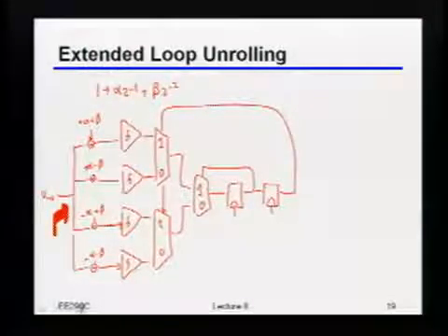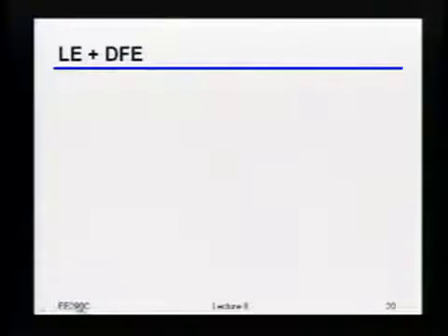Okay, so there were just a few practical issues that I wanted to briefly mention. This one I think we mentioned a little bit last time already, but just to make sure it's clear to everybody. As hopefully you saw from the homework, a lot of times you'll actually combine a linear equalizer with the DFE. And in some senses, sometimes you'll even just build the DFE to make life easier in terms of actually doing the linear equalization. Okay?